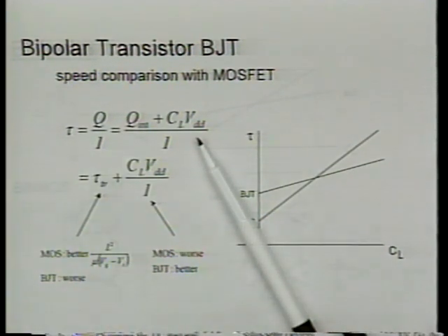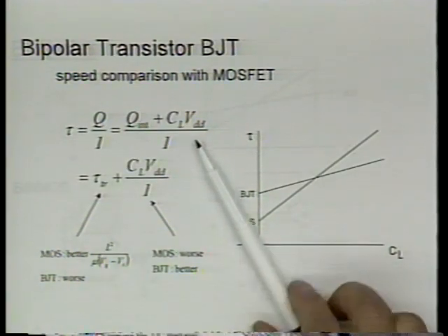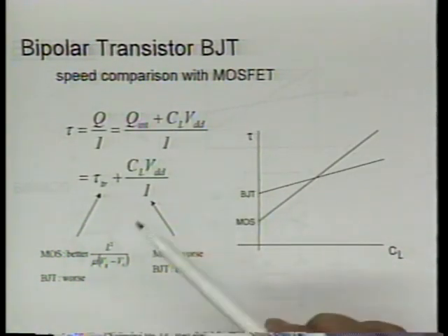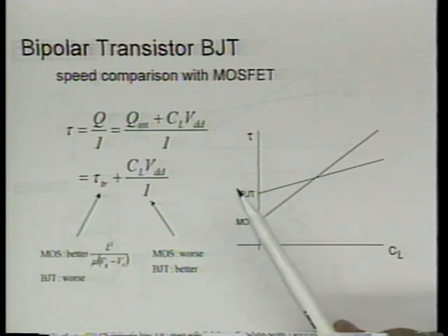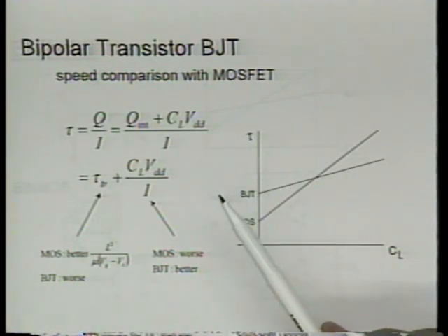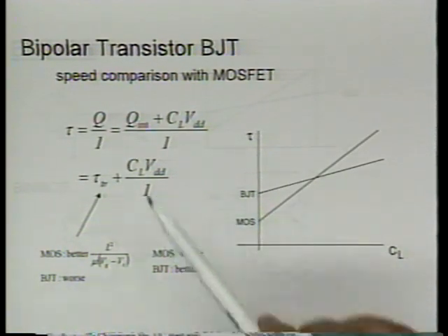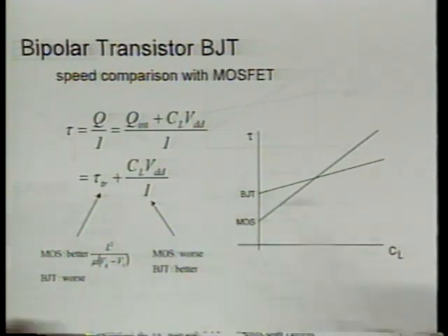In the case of MOS, we didn't go through this detail because we just called it C. Whether it's intrinsic or extrinsic, it's all just capacitance. Junction capacitance, overlap capacitance, the gate capacitance of the next stage, or interconnect, it's just capacitance, right? Now, it turns out the bipolar transistor is a little more complicated.